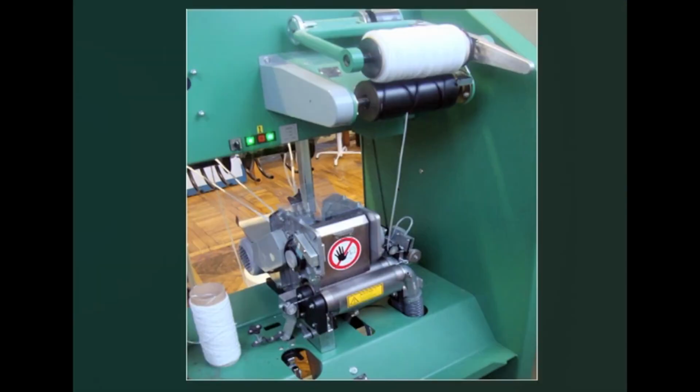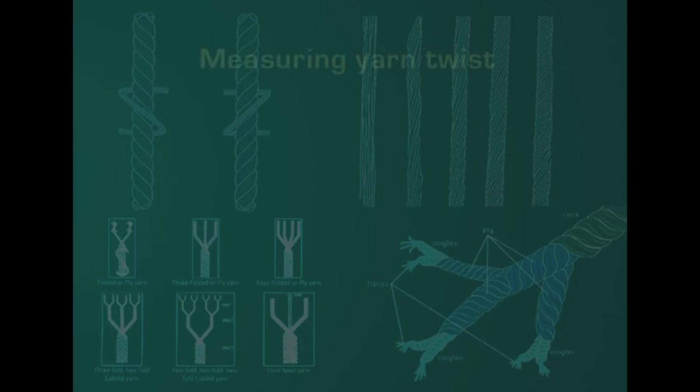But if a low twist factor is given to a fabric or a yarn, it gives a very soft handle fabric, but the yarns are bulkier, more hairiness is present on them, and they reduce the yarn's tendency to snarl, and an increased output can be seen with the same rotor speed, because the number of turns is low.